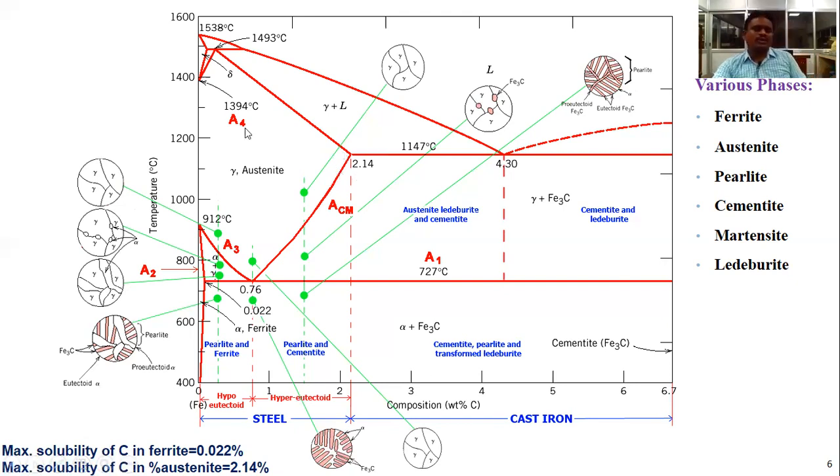As compared to alpha iron, gamma iron has great vacancy in between the atoms in the FCC crystal structure, which can absorb a large amount of carbon with iron atoms. Since it also consists of a limited amount of carbon, it is a ductile material with a high toughness value.